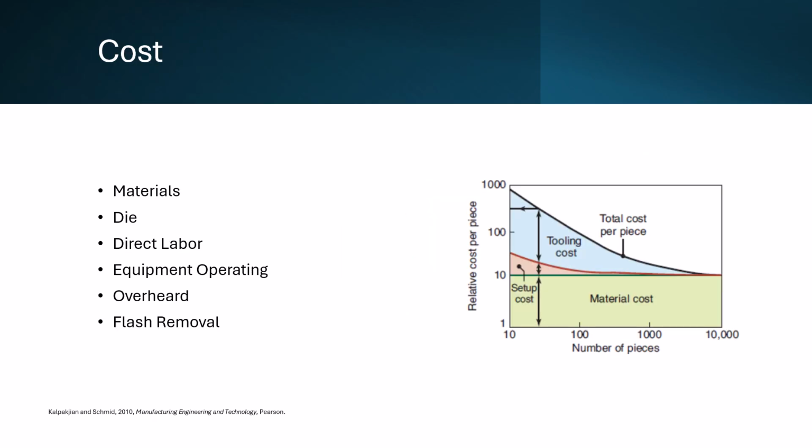Lastly, we examine a cost model for forging. Since today we are discussing hot forging, the estimates presented here are only for conventional dies and parts made with hammers or forging presses. Materials have the largest contribution to forging cost, at about 50%. Unfortunately, due to factors discussed such as flash, a lot of the material cost ends up being waste. Dies come in at about 10% of the cost, though this will change depending on complexity and how many total pieces are made.